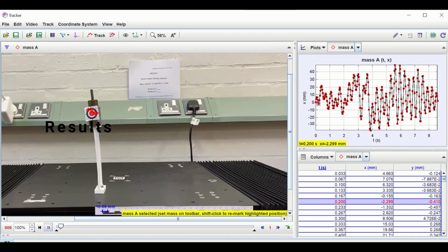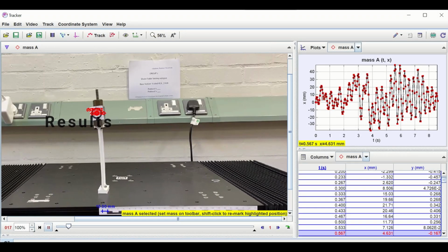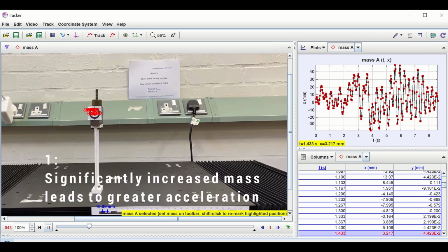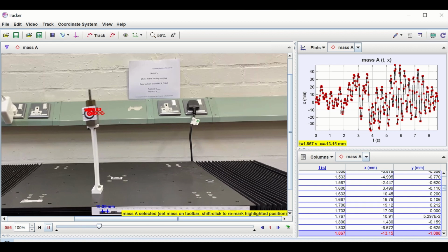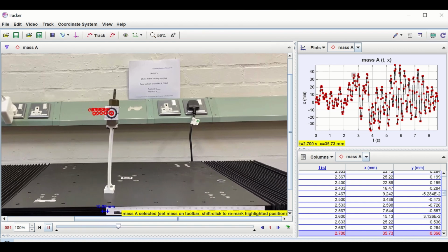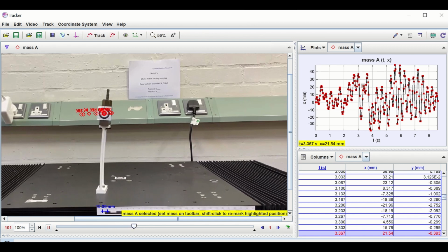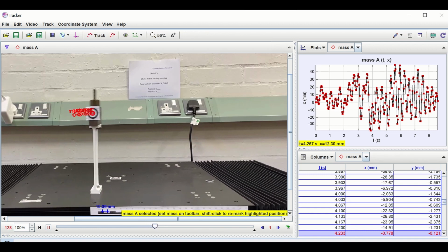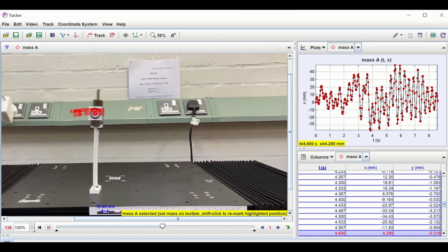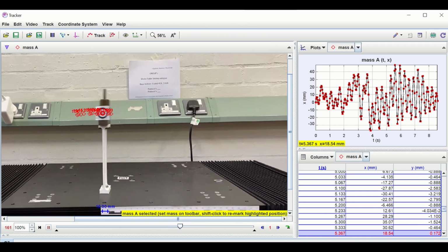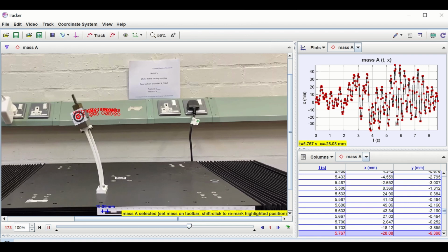the estimated 14 mm. The first possible cause for the difference is that the actual mass of the structure is significantly larger than what was considered for the simulation, which was 4 grams based on its dimensions, fill percentage, and printing material. However, measuring the final printed structure, it actually weighs 16 grams, an increase of more than 400%, which could explain the drastic increase of the displacement between the estimation and real test results. This is because the greater mass causes a larger force to be exerted on the structure for the same acceleration.